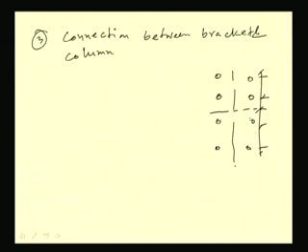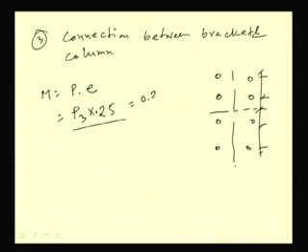Okay. So, first we will find out M is equal to P into E. So, the moment coming to the bracket, if we consider the permissible value on this joint is P3, then P3 into 250 mm, that means 0.25 meter. So, this is the moment, that means 0.25 P3 kilonewton meter, if P3 is given in kilonewton.